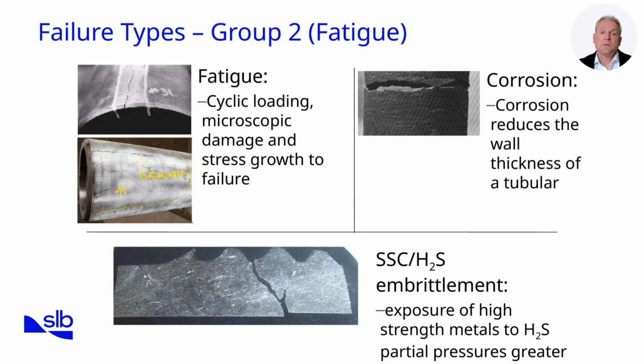Fatigue is the most common and insidious cause of drill string failure. Unlike overload failures, which occur instantly, fatigue develops over time through the gradual accumulation of microscopic cracks. These cracks typically initiate at surface imperfections such as scratches, corrosion pits, or stress concentrators at the thread roots of connections. Each rotation of the drill string introduces a stress cycle, and in deviated or horizontal wells, these stresses are compounded by bending in doglegs.